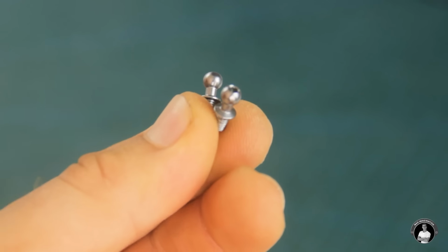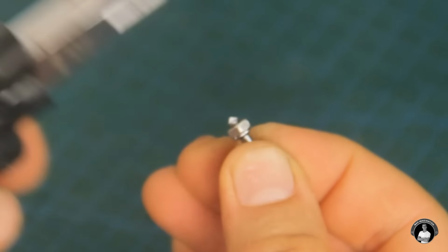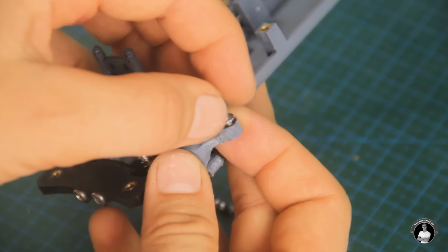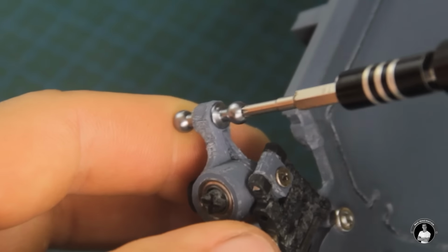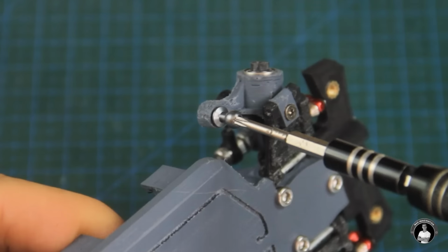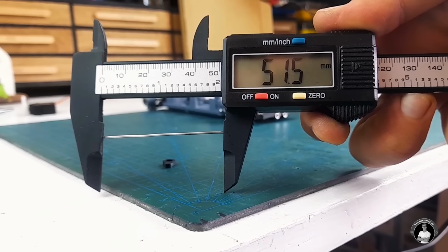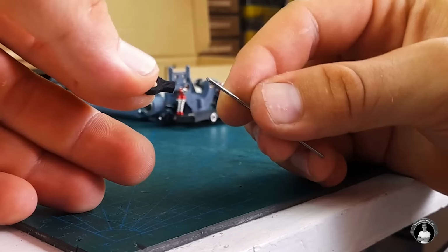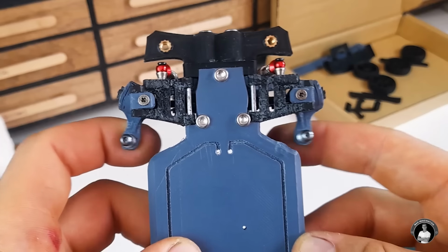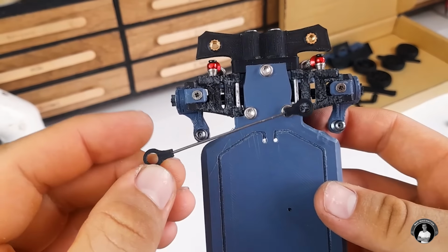To complete the steering mechanism, let's take 3 of these ball screws, sand off enough of 2 of them to fit into one wheel cup and one for another cup's arm. We can now make the steering link piece, which consists of the right length of wire and 2 ball cups, which then link the 2 ball screws below.